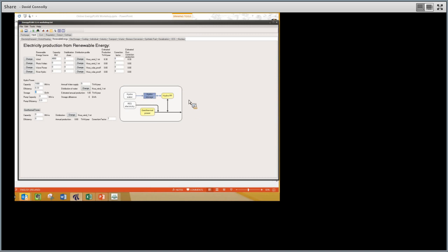So just to recap, river hydro occurs when we can only use the electricity as it's generated. Conventional hydro occurs when we can control the output of the hydro power plant. In addition to that, some hydro power plants actually install pumps so that they can pump some of the water back into the upper reservoir of the dam once they have consumed it. So you can also add in a pumping capacity if you want to be able to send energy back into the reservoir after it has been consumed. But this is not pumped hydroelectric energy storage. This is a hydropower dam facility that has the ability to pump back.